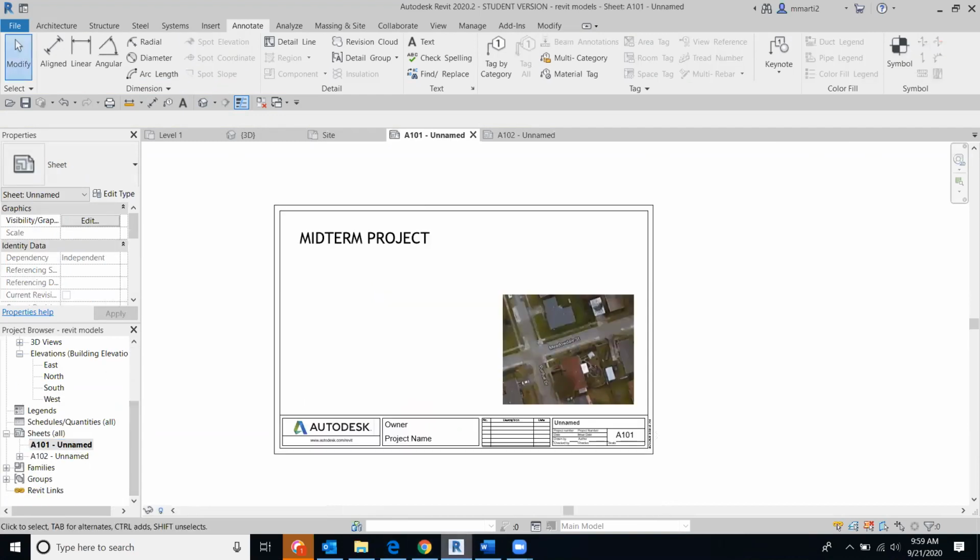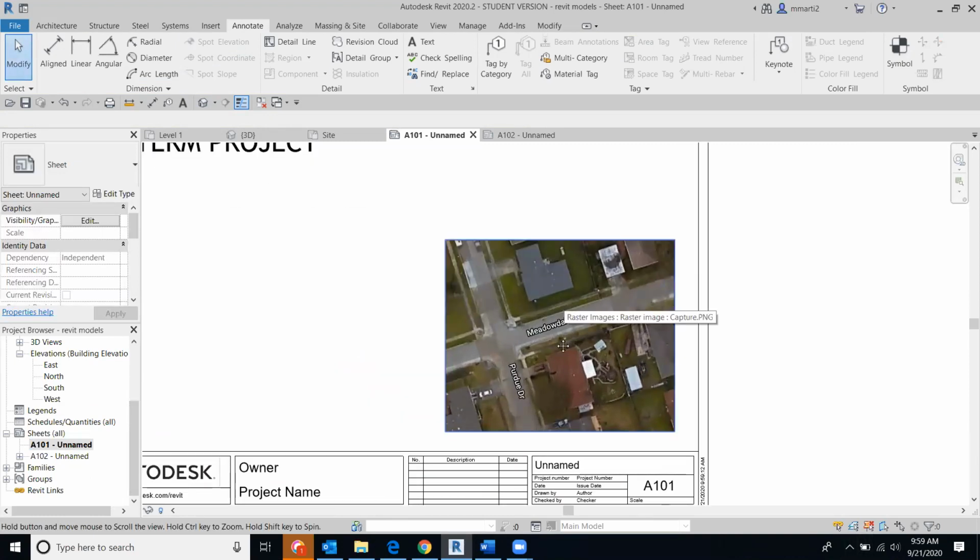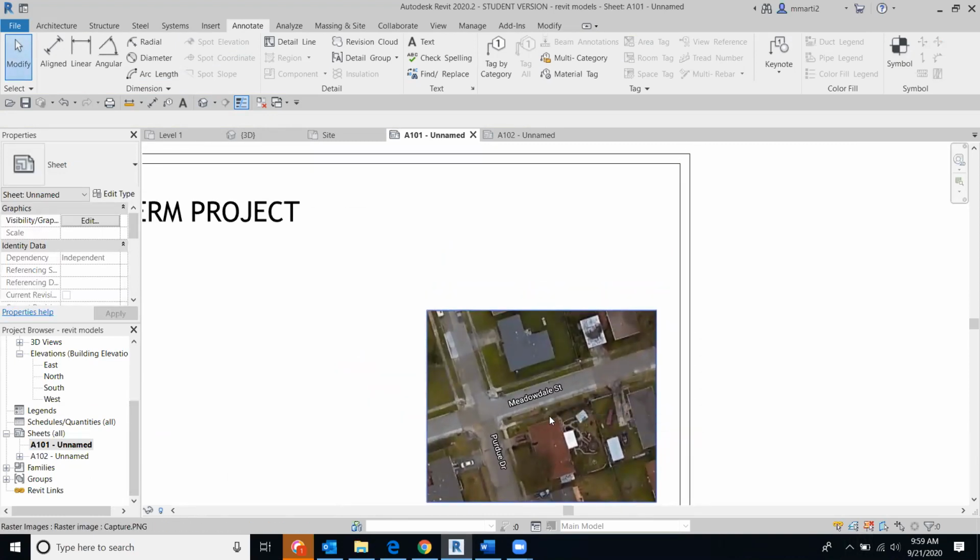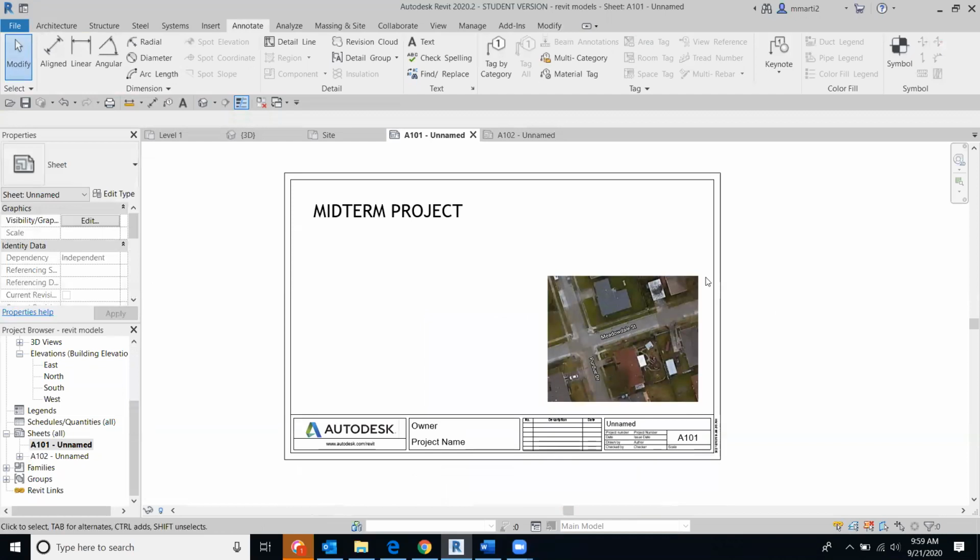So if we go back to our sheet, say on here from my sheet, true north is actually this way. So if I rotated the drawing, so it's facing actually west, my north arrow would just indicate the direction of true north. It's really good if you have this Google Earth view to orient that north arrow, but you can just have that laid out with just an N on your document, which would be fine on your site plan.